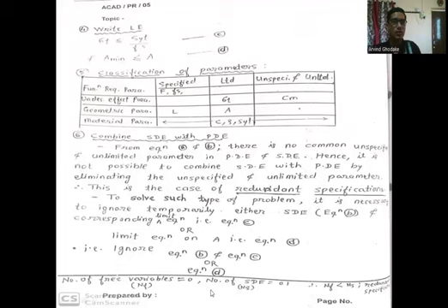Next one is writing of the limit equation, that is sigma T is less than or equal to SYT upon Fs, and A minimum should be less than or equal to A. So equation C and equation D are called the limit equations. And next we have a classification of the parameters: specified parameters, limited parameters, and unspecified and unlimited parameters.